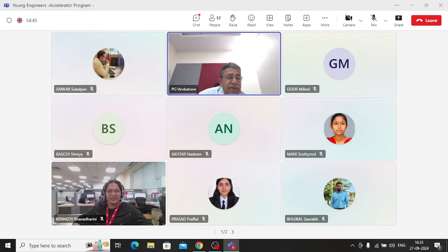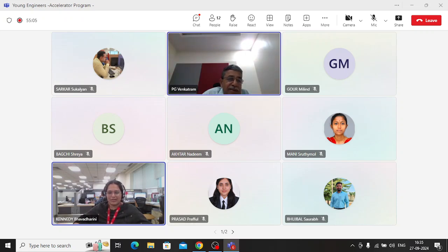One reason. Okay. I'll grant you that it's a small reason. How much do you think the cantilever deflects under the wheels of a vehicle? How much do you think the cantilever is typically from the bearing to the expansion joint, if it is there? It may be 1 meter. The center of the bearing to the expansion joint generally is of what order? 800 to 1.2 maximum, 1.2 meters maximum. Out of that 1.2, you also have the projection of the web a little bit. And then you leave maybe about 500, 600 mm. That 500, 600 mm cantilever will deflect.